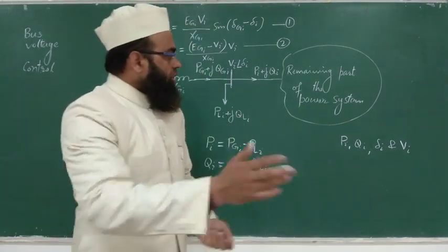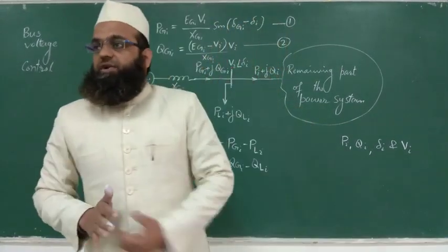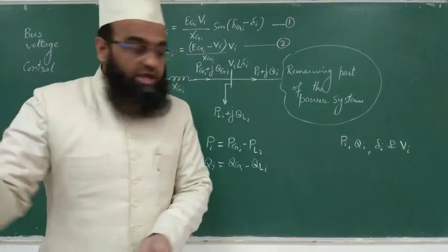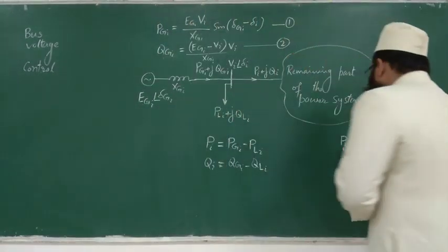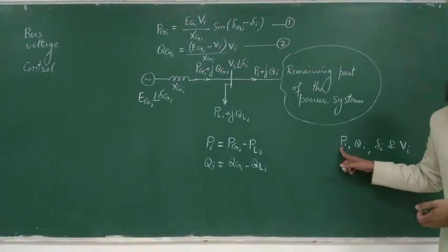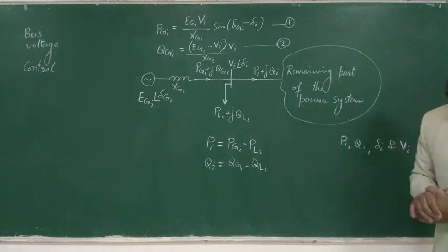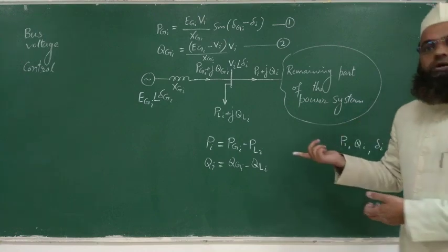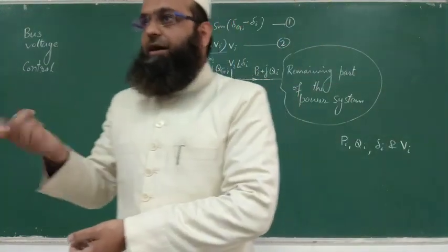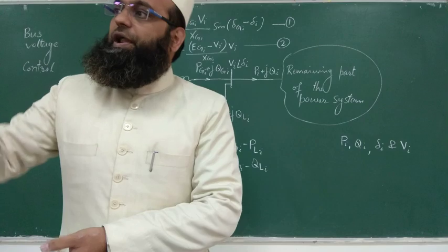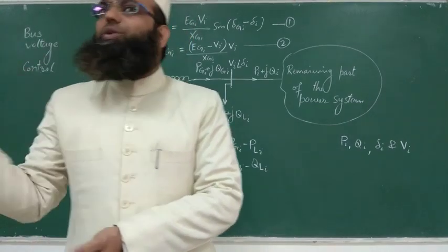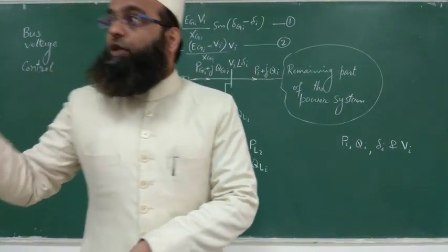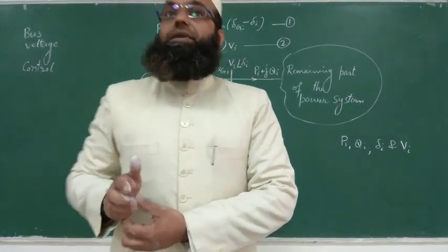So for the values of these variables obtained after load flow of the power system, if this demand is more than what you are having, what will we do? If this demand is more, then it means you need to adjust delta, because this is more dependent on delta. Not only dependent on delta, we have seen in Newton-Raphson also and fast decoupled like that. So mainly we need to focus on delta. And how to adjust delta?